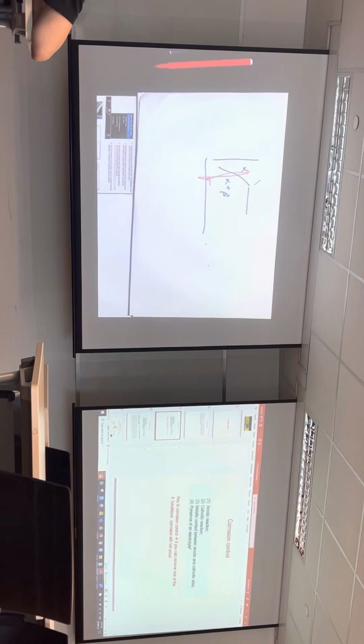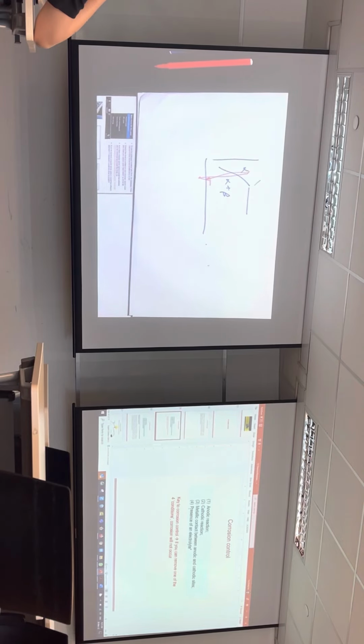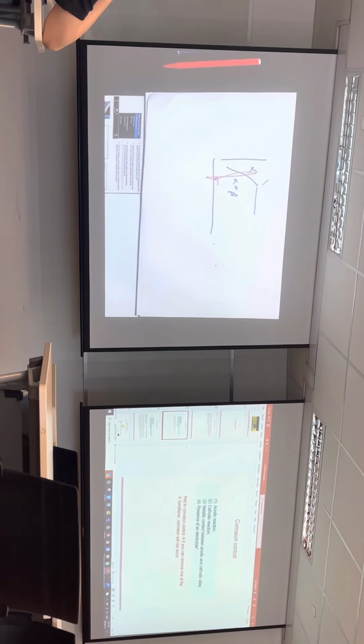So you understand the principle of how corrosion happens. Then when you look at what they do, when they paint, they're actually preventing the electrolyte from touching. So they are actually breaking the circuit that lets corrosion happen. If you think through all the general corrosion techniques, it all boils down to this. If not, you will always be remembering a lot. All those things that you apply are based on this fundamental principle of corrosion. You can actually remove any one of them. Make sense?